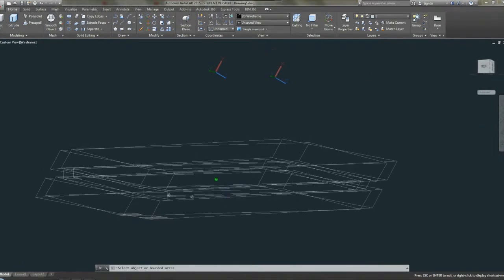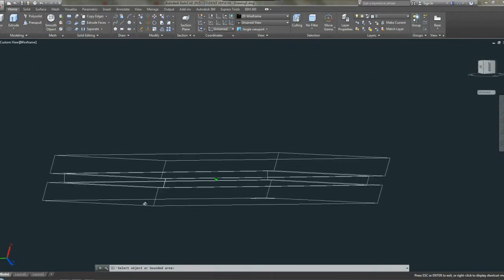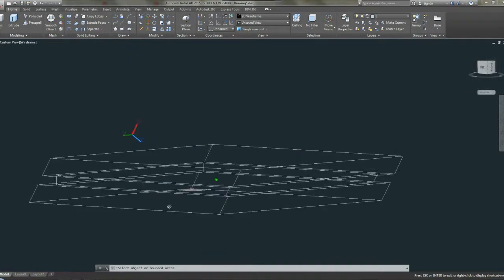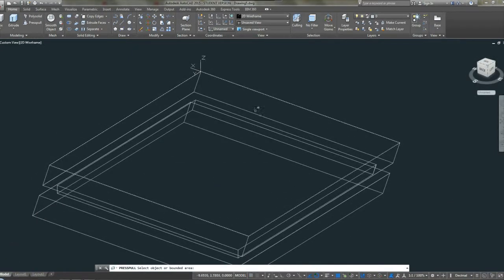And then what I basically did was just start cutting off the air vents, and where the light goes, you just cut it off. It's kind of the same way what I've been doing. I used copy edges, I moved the lines, and then using the press pull tool, I just pulled in or pulled out depending on how much it looked like it needed.